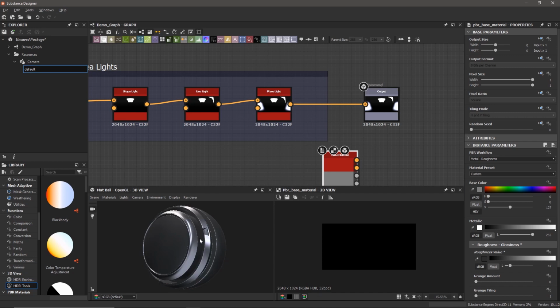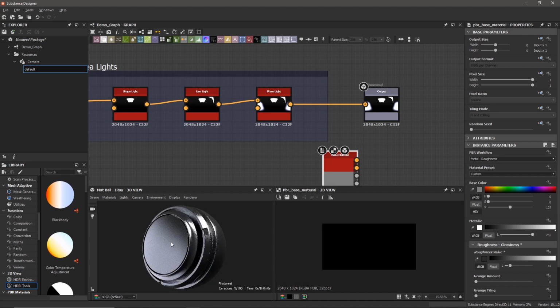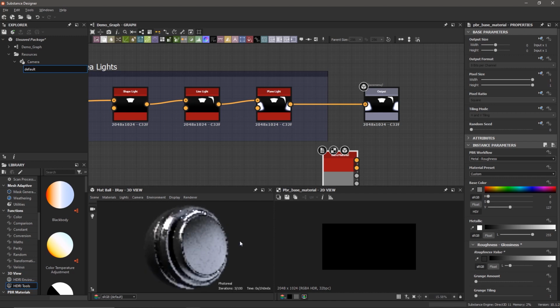So the last thing to set up our working environment here is I'm going to go to the Render tab and choose iRay. Now, if you have a fast enough computer, I think using the iRay render engine is going to give you much more of a photorealistic look. It's okay to be working in OpenGL. It's faster, and you can get used to how its reflections transfer to how your render engine works later on. But I'm going to choose iRay. And now you can see how these reflections are really working with most materials and geometry. And that's why this material ball is so useful, because it gives you those specular reflections, and it looks pretty nice.